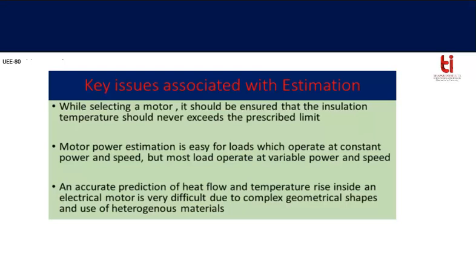Now different insulating materials are placed across the motor. Now if the increase in temperature is more than the withstanding capability of the insulating material, then the insulation will break down. Because of that, there will be a dead short circuit across the windings, or some other unwanted behavior of the machine we will see. So it should be ensured that temperature should never exceed the prescribed limit of the insulating material.